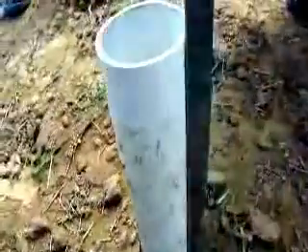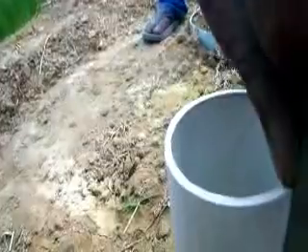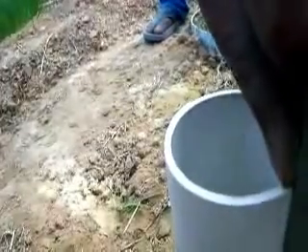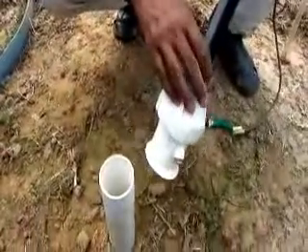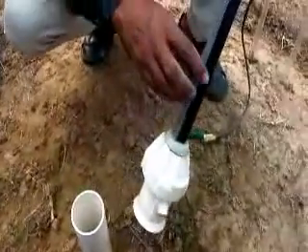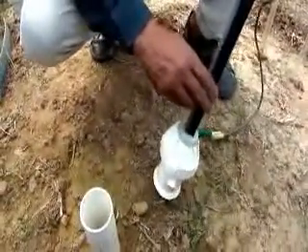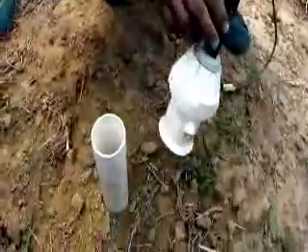It is near about 19 centimeter. You can see 19 centimeter over the ground surface. So 19 plus whatever scale we are interested to find out, just like 30 plus 19. So 49 centimeter, once we are inserting, it will be at 30 centimeter depth of soil moisture measurement.